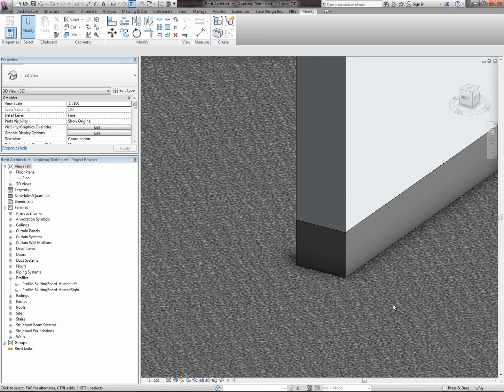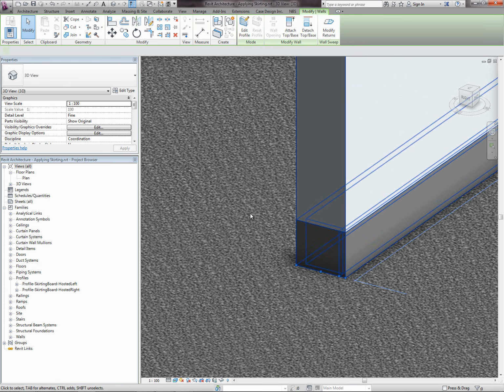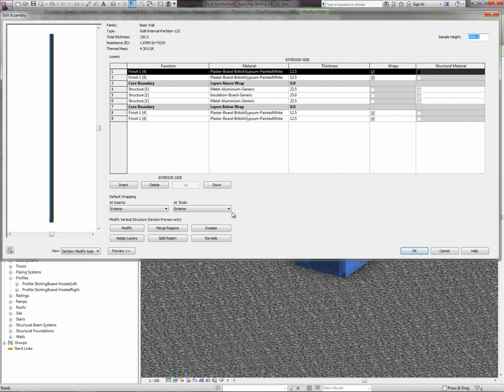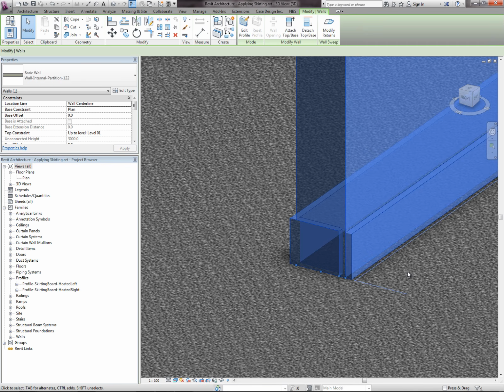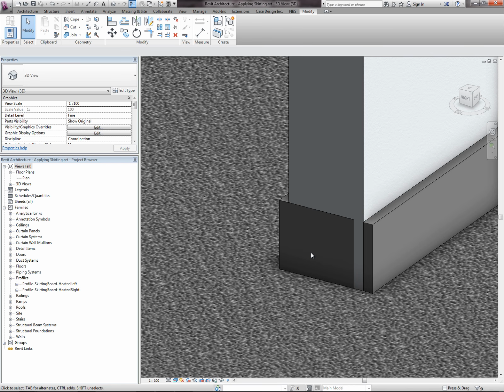Now, you could obviously ask, why wouldn't we start with the profile with lines orientated to the left in the first instance? And the reason is purely because of this end piece. If we were to use this current profile with the lines orientated to the left in the first instance, we would need to add an offset to push it away from the host, which I'll do now. But as you will see, this wouldn't affect the end piece, which would still be recessed.